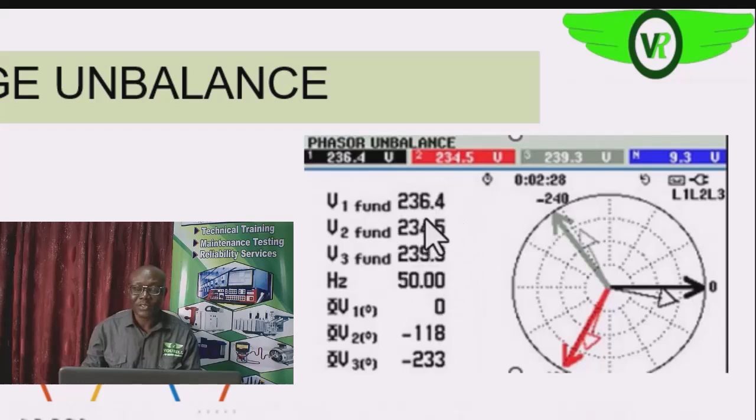For the unbalance, usually what we do is take the average of these 3 voltages and subtract each of them from that average value. Then we use the highest deviation, take the highest deviation and divide it by our average. What we have will become the unbalance in the system.